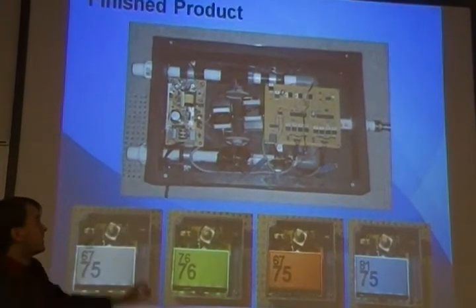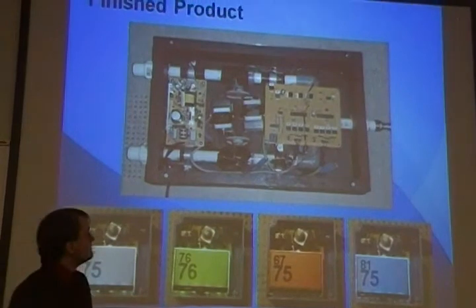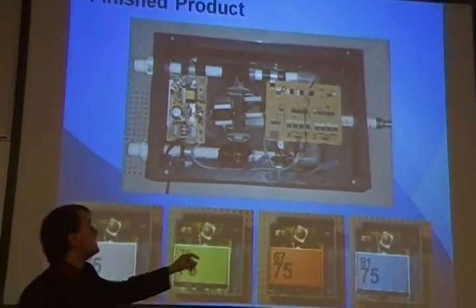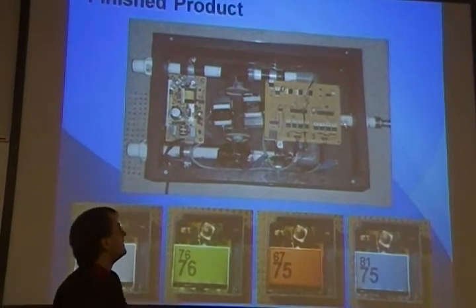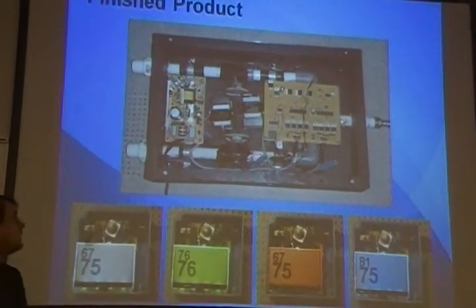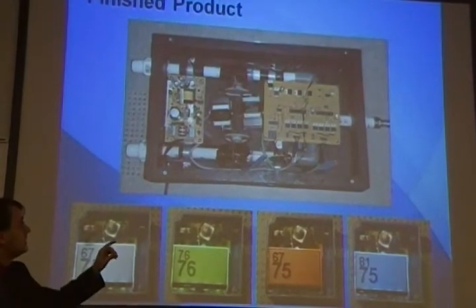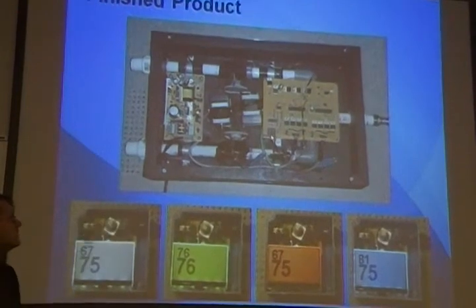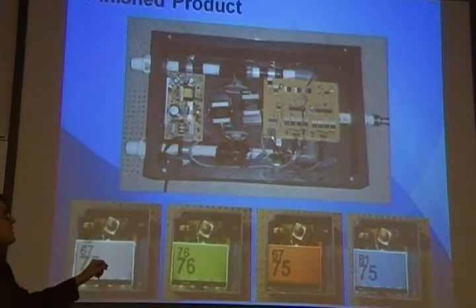You see on the left there is the black one, the main microcontroller. The thermistor is connected on the bottom and goes into the pipe, as you can see. See right there, the thermistors go into that pipe. It's connected to the main microcontroller. And then the main microcontroller also connects to an RJ45 port, which goes through a Cat5 cable to the interface.